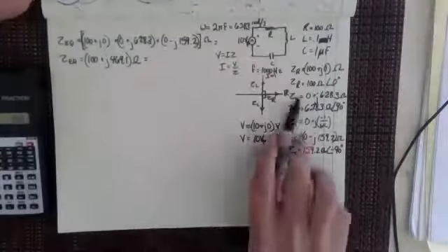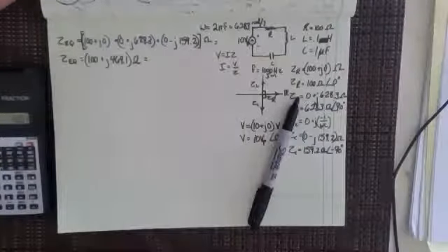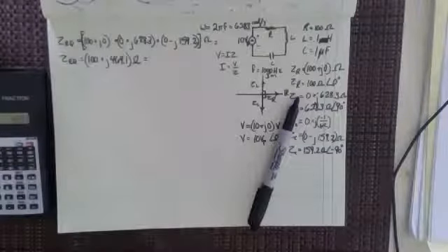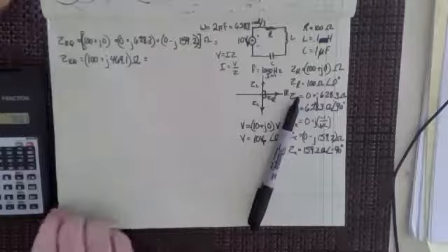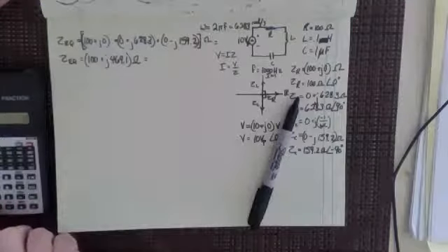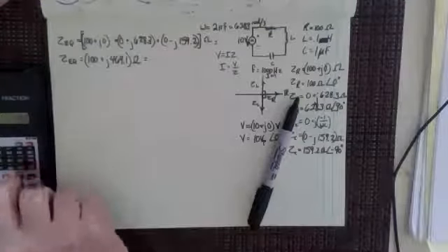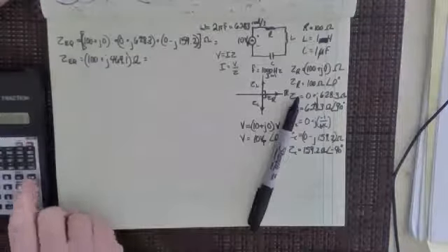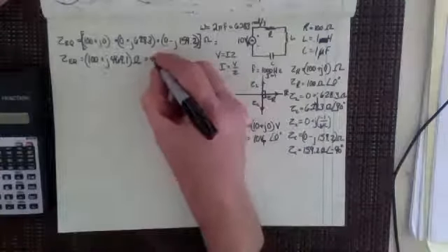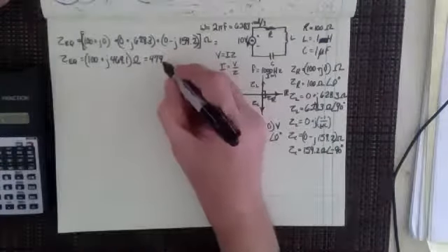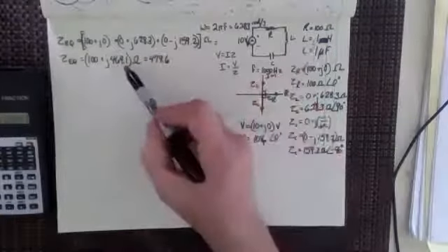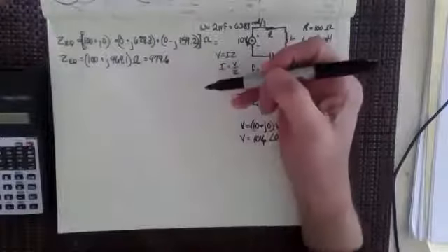So let's go back to this equivalent impedance now. We've got that equivalent impedance in the rectilinear complex number notation, A plus jB, right? But now we want to turn that into a phasor. To do that, we square the one component, add the other component squared, and then take the square root of that, and that gives me 479.6. And you can see that would be about right, wouldn't it? Because the square of 469 is so much larger than the square of 100.